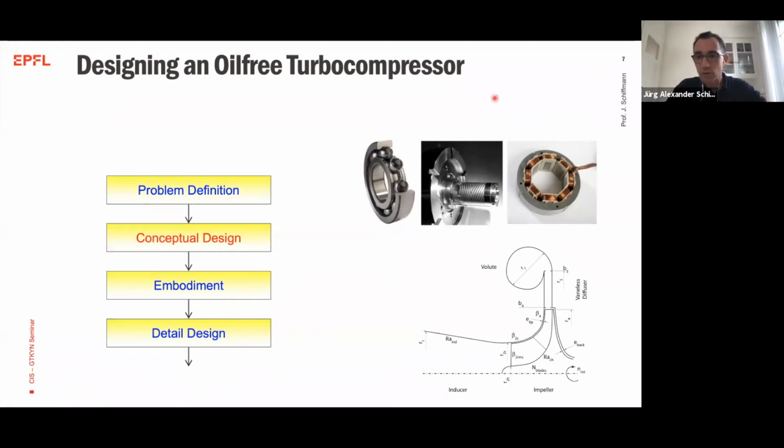So the other technology that remains, which would be a feasible one, would be magnetic bearings, but then they are expensive and also cumbersome, so they make the system rather big and bulky. And the alternative would then be gas-lubricated bearings, where we would use the process gas in the compressor directly as a lubricant for these high-speed rotors.